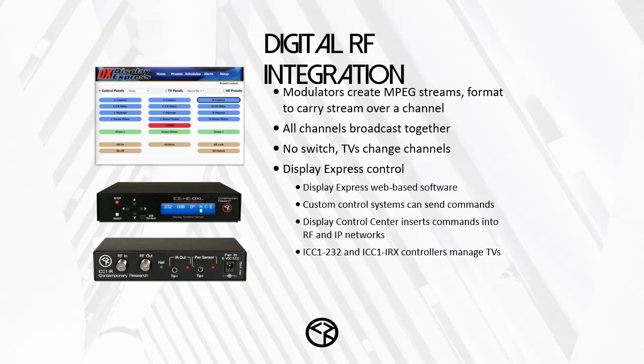At the same time, you could use Crestron, AMX, Extron control systems to create your own custom commands as well. In the middle, instead of a switch, there's the display control center, and that receives the commands over IP or RS-232 or USB and formats them into a control channel that's distributed through the RF network.